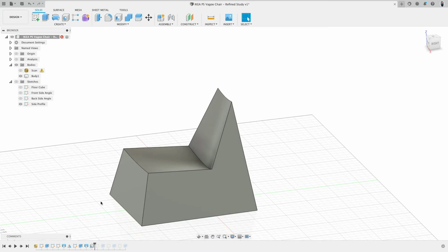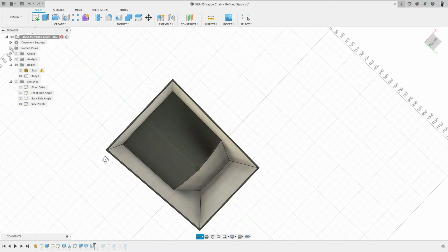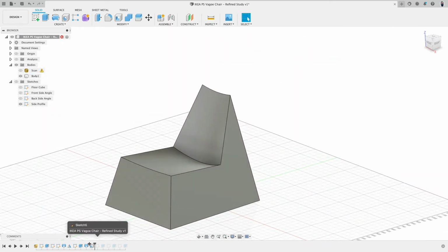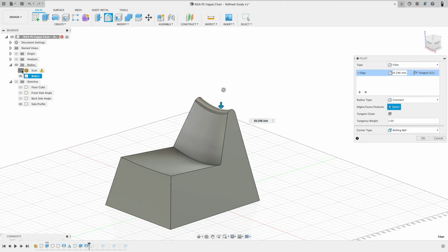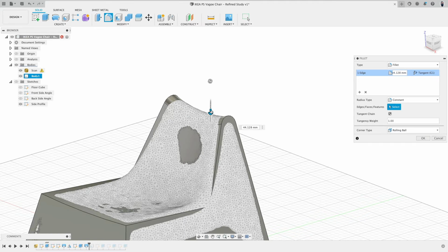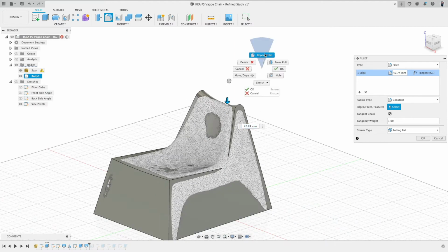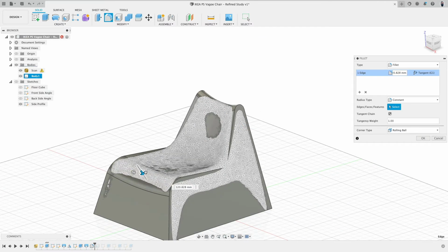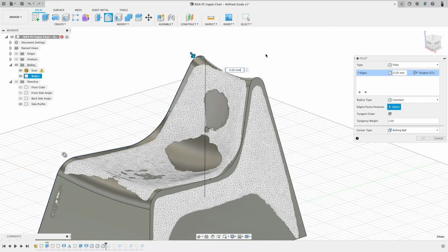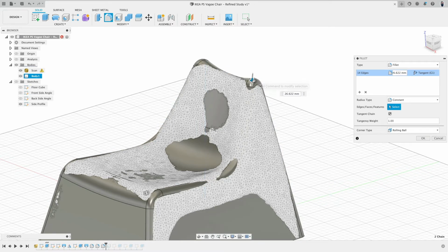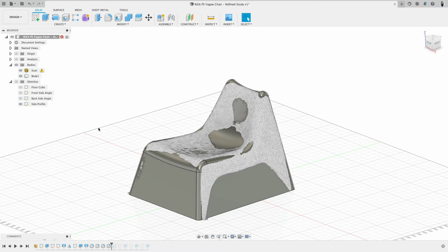Then here comes the shell command. Okay, so the shell command is happening way too early. So let's go back to here. We need to round everything first. This will be rounded there. Right click, repeat. This will be rounded. Right click, repeat. Here's that edge. There, right click, repeat. And then these two edges here, we round them too.